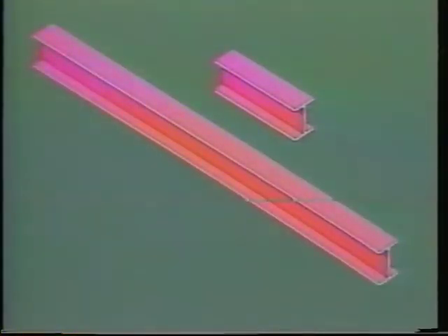For a very stocky beam, the plastic moment is significantly less than the critical moment, and instability does not occur. For a very slender beam, the reverse is true, and the beam will fail by elastic instability. The response of very stocky and very slender beams is quite clearly defined, and relatively simple to analyse, at least in an approximate manner.